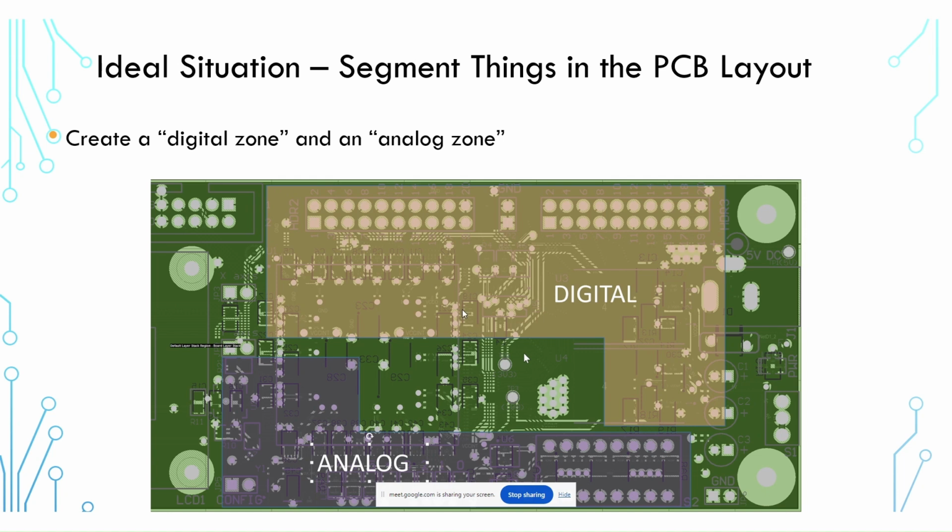So this would be your interface, for example, from your microcontroller that would then be used to control whatever analog stuff on your board has a digital interface. Most commonly, that is, for example, your microcontroller talking to your DAC or your ADC, or maybe a programmable amplifier or some other component like that. This no man's land would be the region where you want to route that stuff.